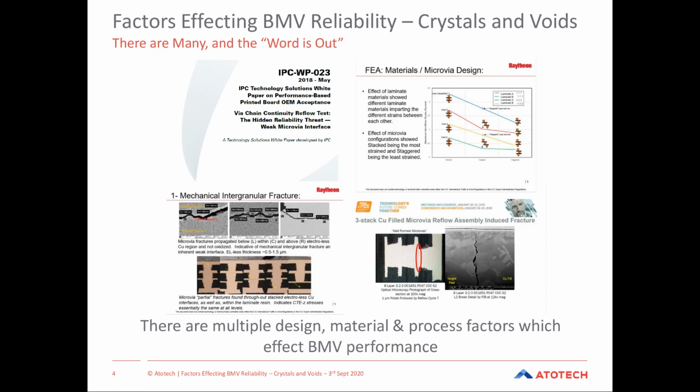And that's essentially brought us to where we are now, where there's a lot of companies, both board manufacturers, chemical suppliers, test houses, are looking at wires and trying to understand design criteria that affect them, whether that's dielectrics, staggered wires versus stacked wires, layer counts, the works. So there's a lot of papers looking at design characteristics. There's equally huge numbers of papers, some from ourselves, looking at failure and trying to learn from dead bodies, looking at failed wires to try and understand things.